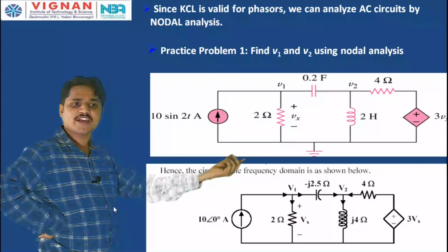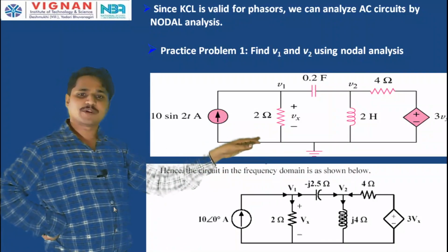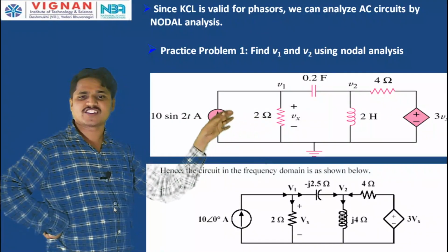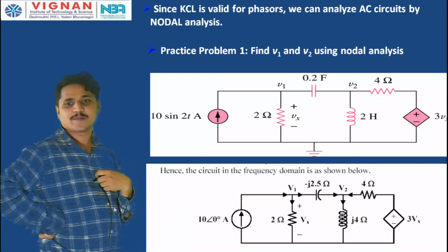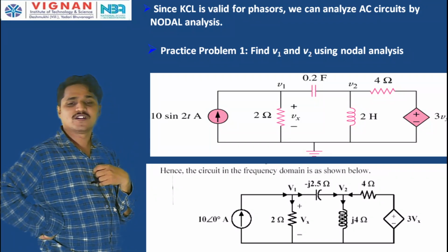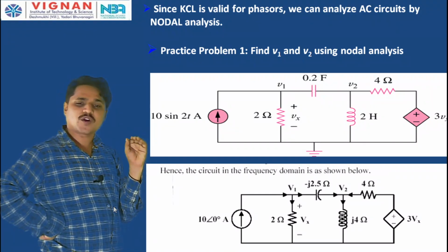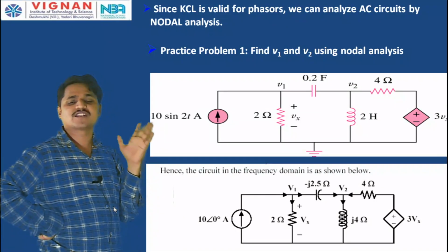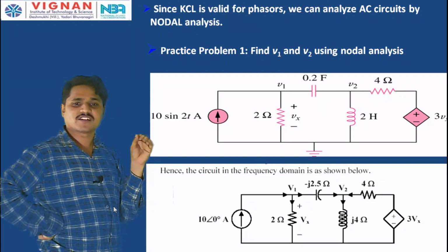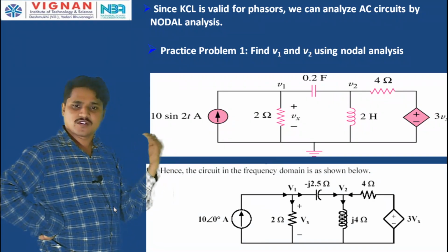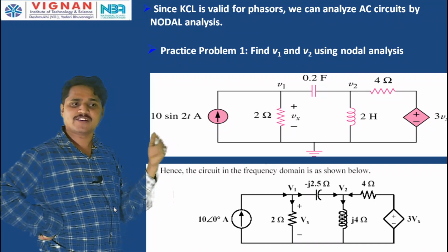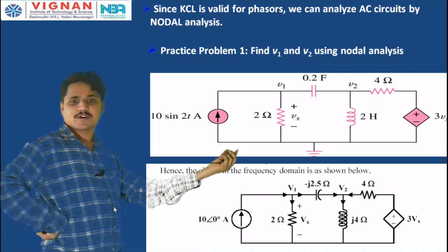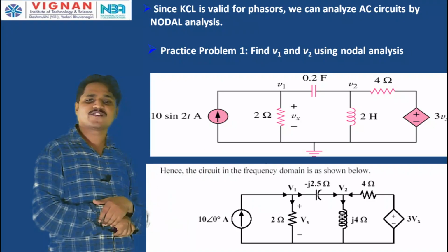Now, ground, okay. Ground is also a principal node because how many elements are connecting? Current source, resistors, an inductor, and the dependent voltage source. So, 4 elements are connecting. See, the reference node you have to select such that the node which connects the highest number of elements is selected as the reference node. So, here I am selecting this node 3 as the reference node. So, ground.